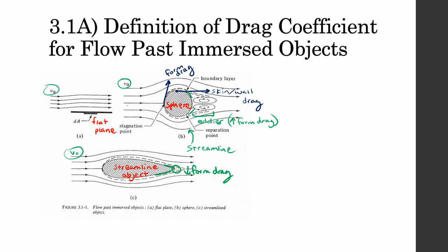So basically, we have these key forces, and another point we can consider is something called the stagnation point, which is this right here in the center, where it looks like the streams are separating, going above and below the object, and the key characteristic here is that the velocity is 0. Some common chemical engineering applications of these systems: this could be used in a drying and filtration flow system, or we can also have a flow in tubes for a heat exchanger system. So heat exchangers as well. These are some common uses that we might have.